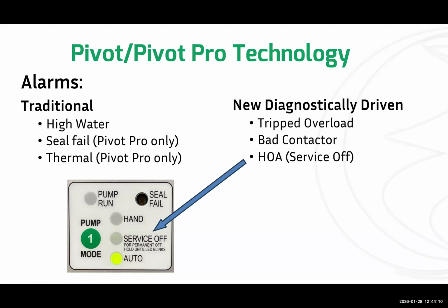After 4 hours, if you have not taken that pump and put it back into service, if you haven't put it back into auto after 4 hours, it will sound an alarm. And it says, hey, this service call is taking longer than it should. Make sure you know that this thing is still in off. So it basically is a, don't forget it's off kind of an alarm.